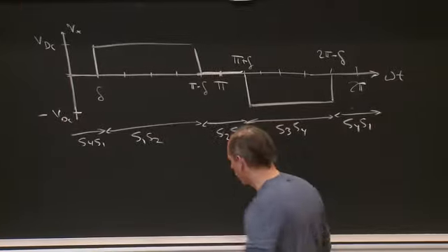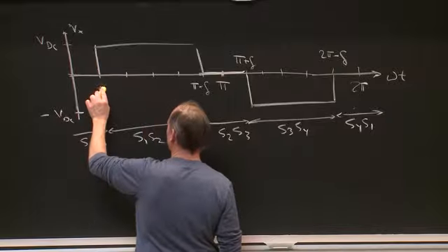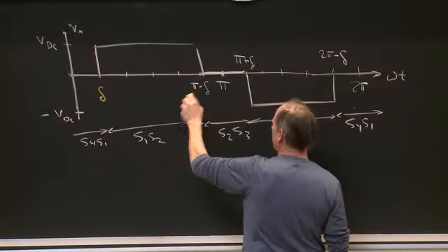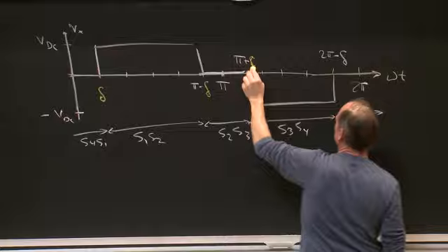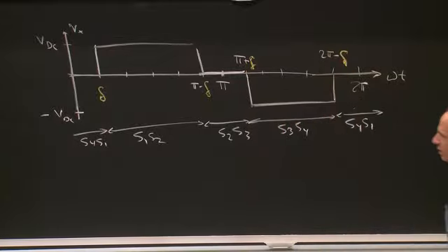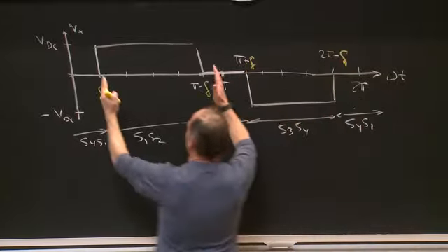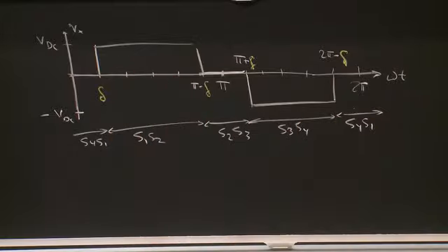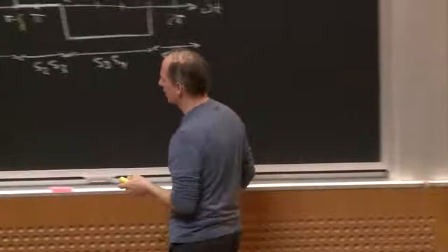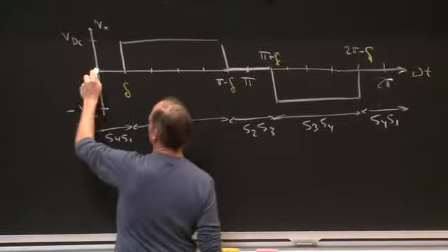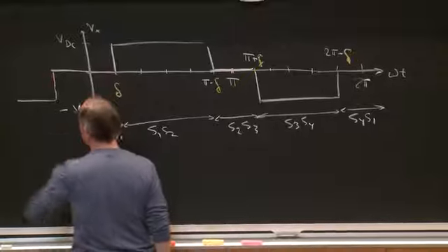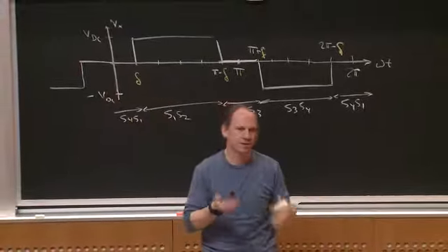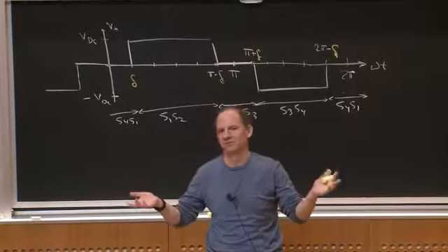And we said my one control handle in this pattern, if I use it, is this angle delta. And by picking delta, we can do a few things. One thing we said we could do is if I make delta bigger, the fundamental component gets smaller. And if I make delta smaller, the fundamental component gets bigger. So I can control the fundamental of the output that way. The other thing we said we could do is control the harmonics, right? Because for an odd waveform, and I'm only picking it to be odd just because it makes the Fourier series description simpler, right?